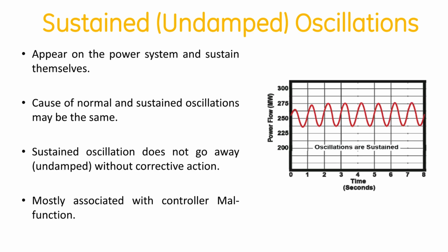Extremely vulnerable. The moment a second event hits, even a smaller one, while the system is already dealing with that sustained oscillation, it could push it over the edge. It very easily could. That sustained mode can quickly transition into the truly catastrophic category, negative damping. Plus, sustained oscillations can mask underlying weaknesses or other potential problems. There's a serious red flag. Okay, that makes sense.